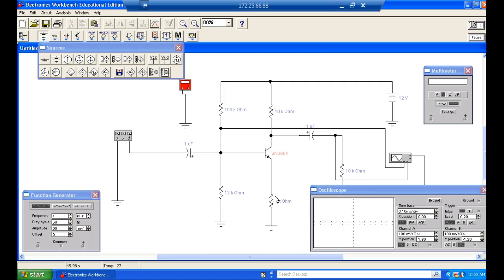But capacitors, they short, or they open, or they become what? They become leaky, and that's true with any solid state device. It can go bad 3 different ways. But a short is pretty easy. Even a diode, if a diode is shorted, what you measure on the cathode would be exactly what you measure on the anode, right? Exactly, not a millivolt difference. And that would tell you that the thing is shorted.